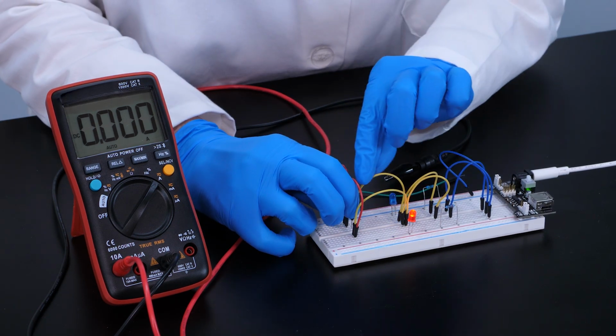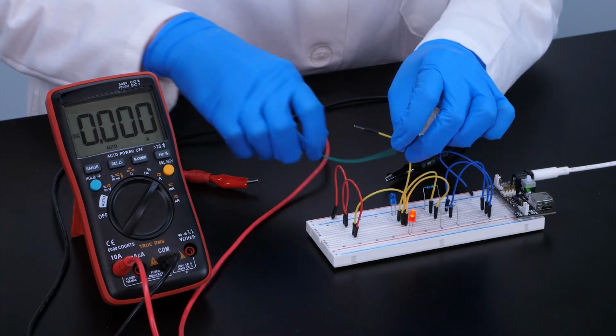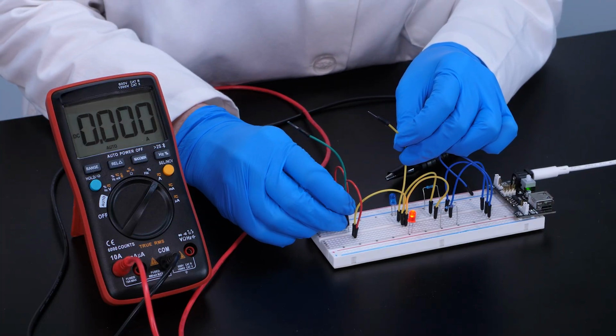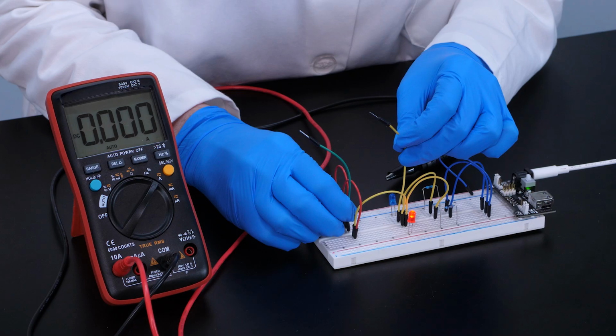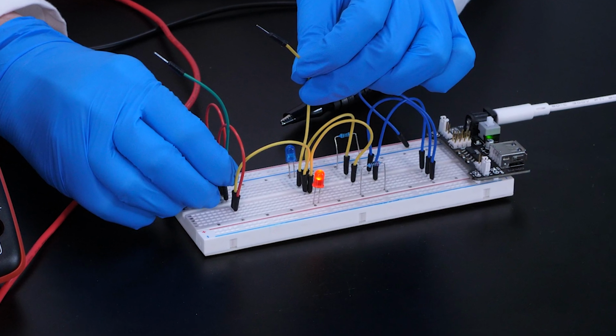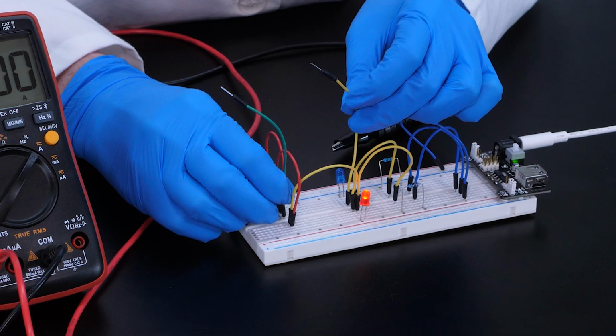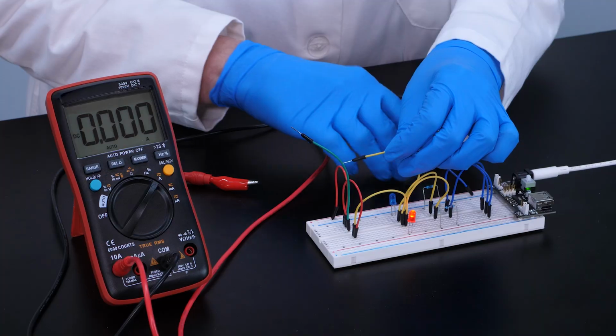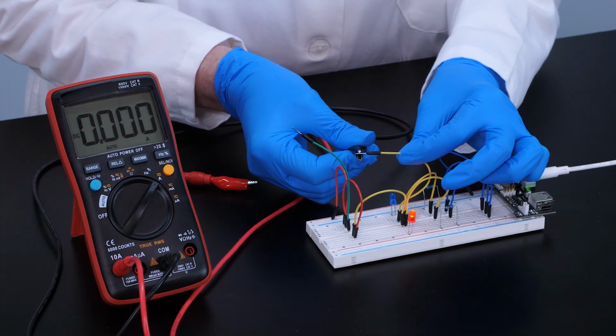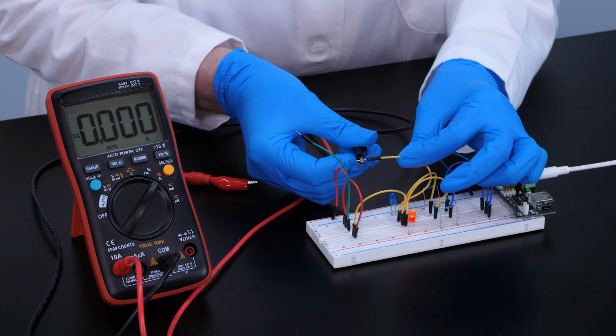After replacing the yellow jumper wire, we can measure the current through the second load. We unplug the yellow jumper wire at the end of the second branch and plug in a green jumper wire where the yellow jumper wire was plugged in. Notice that the blue LED turned off as soon as we interrupted that branch of the circuit, but the red LED stayed on.